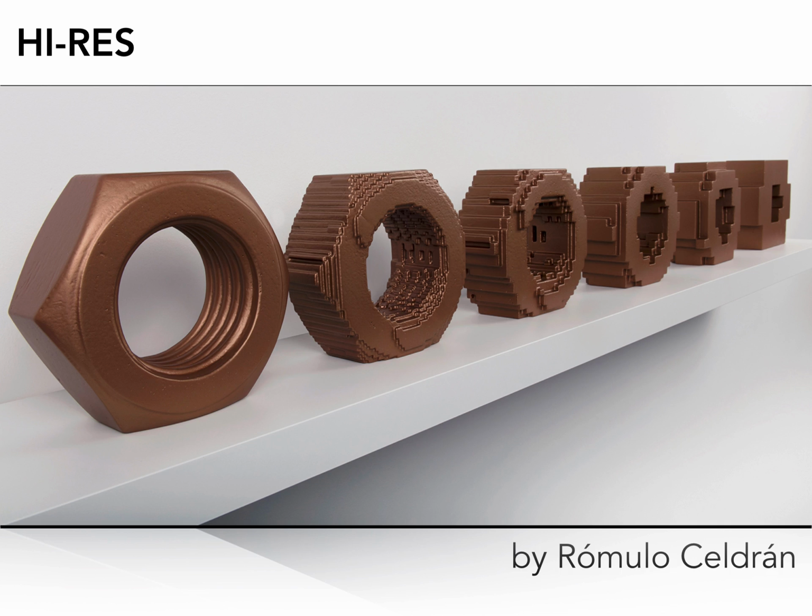And what you see here is one of the things that we will do, right? Captured in art. We will do something called mesh convergence. So sometimes what we want is to see how the error in our approximation goes away as we refine the mesh. So you would expect that as you refine your mesh, the error with respect to an exact solution gets smaller and smaller, and we will study that error. So later, hopefully, when you grab a finite element package, then you can see how that error goes away, because you can actually predict what would be the exact value of your strain energy, for example, okay?